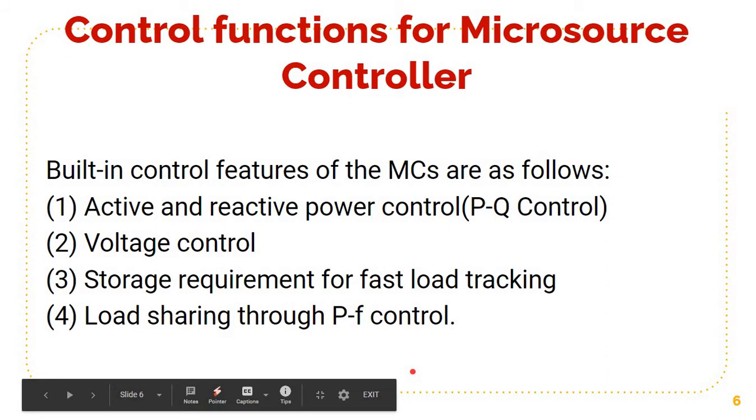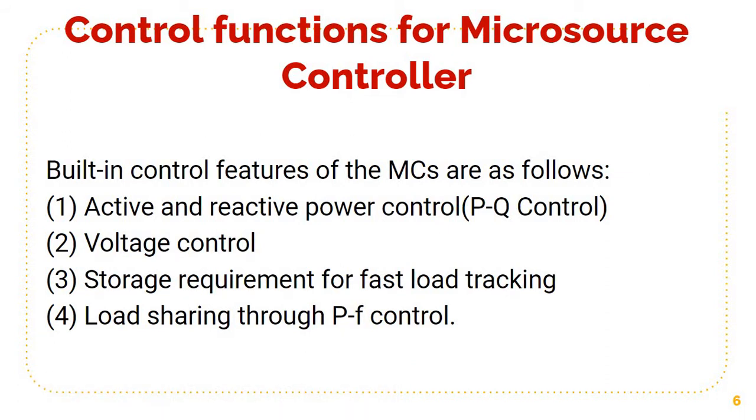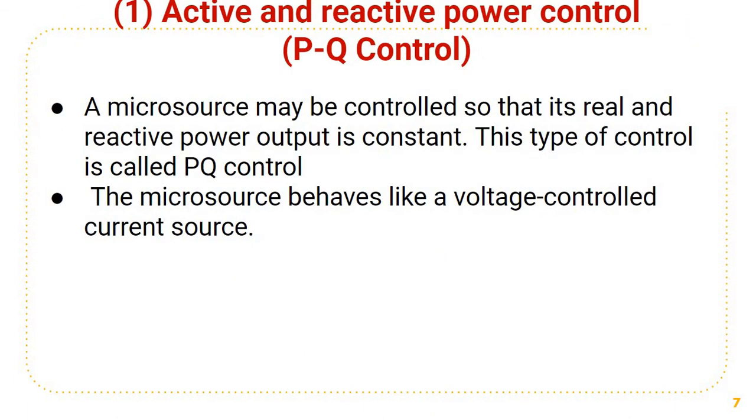Now the built-in control features of the microsource controllers are active and reactive power control, or we call it PQ control, voltage control, storage requirement for fast load tracking, and load sharing through PF control. So these things we will discuss today. The first one is the PQ control, or active and reactive power control.